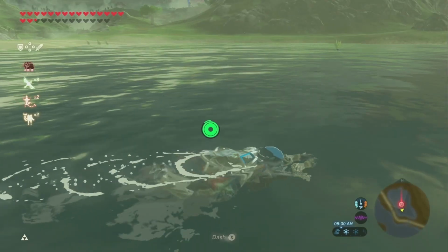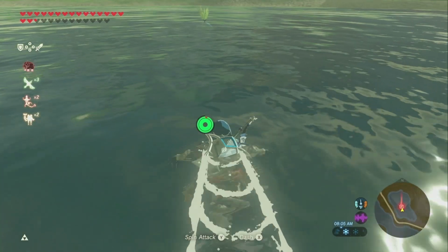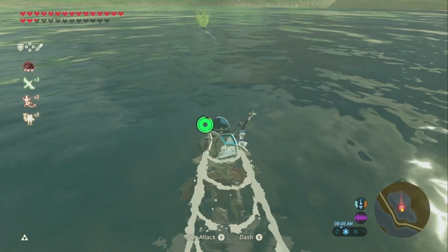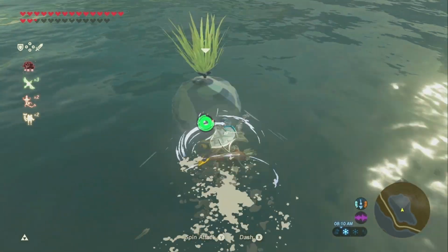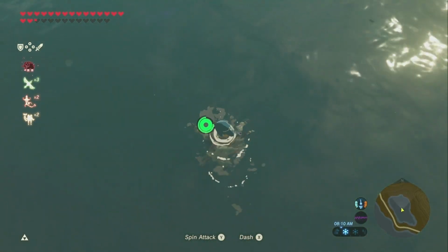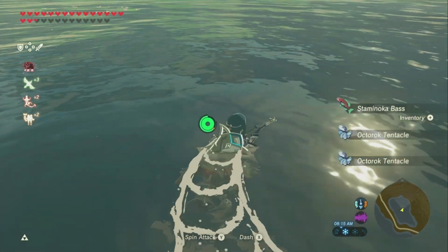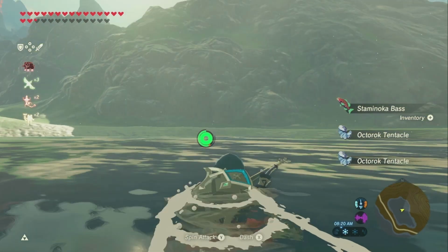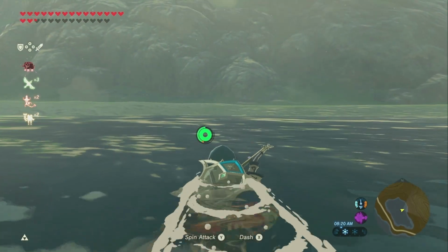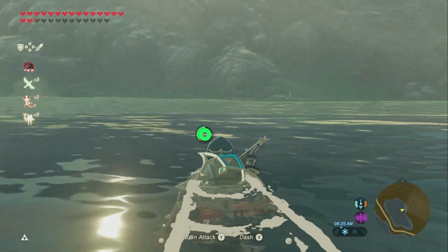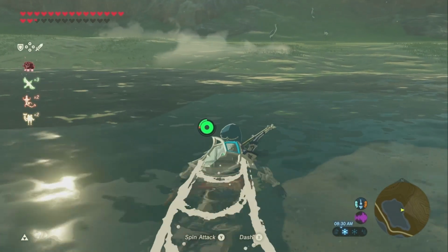Baffle collapsed or missing, gas or oil. The baffle, or turbulator as it is sometimes called, is typically a stainless steel helix installed in the flue passage to slow down the gas or oil exhaust products as they move up through the water heater and out toward the vent connector. The longer the exhaust products linger in the water heater, the more heat will be transferred into the water.